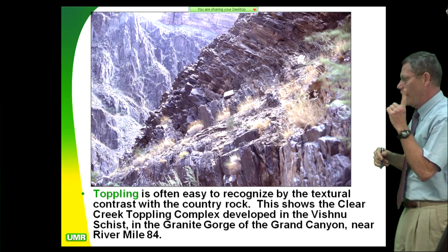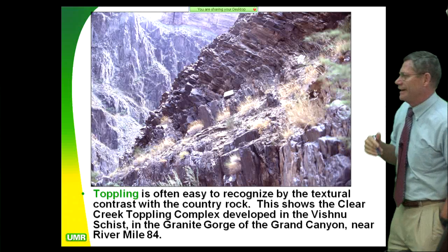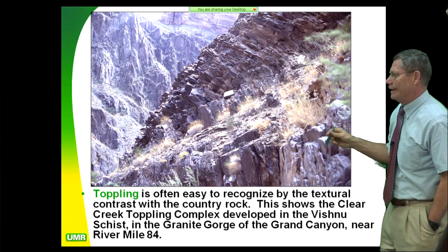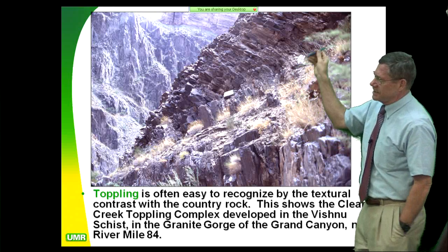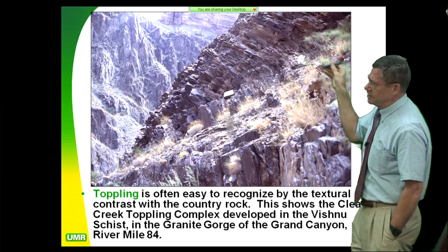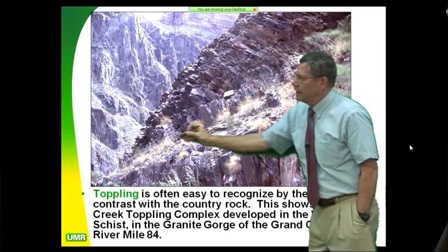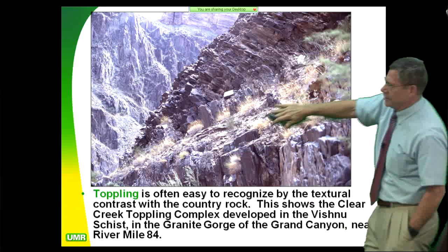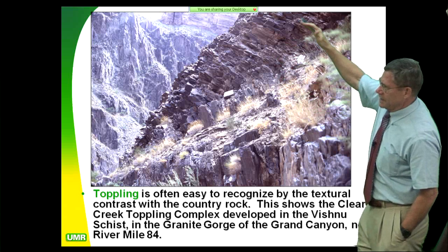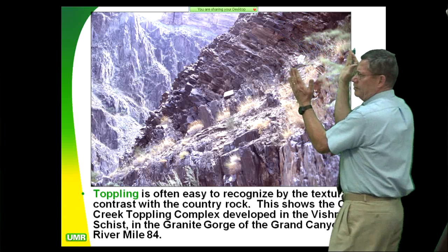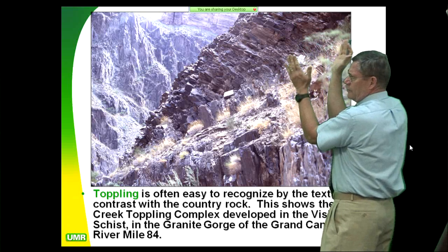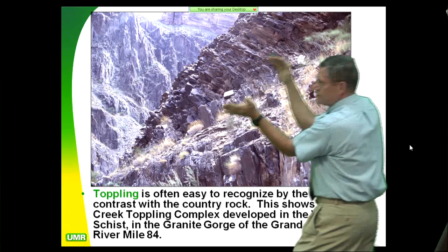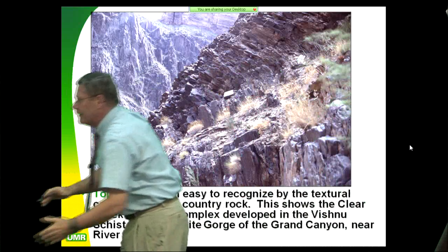We knew about one only, and we ended up finding about 26 different ones there. But this you can actually see, there's the hinge line right here. And what's happened here, this is an untoppled surface, and the toppling failure probably got triggered by an earthquake, and it detached and just catastrophically went down in the canyon.